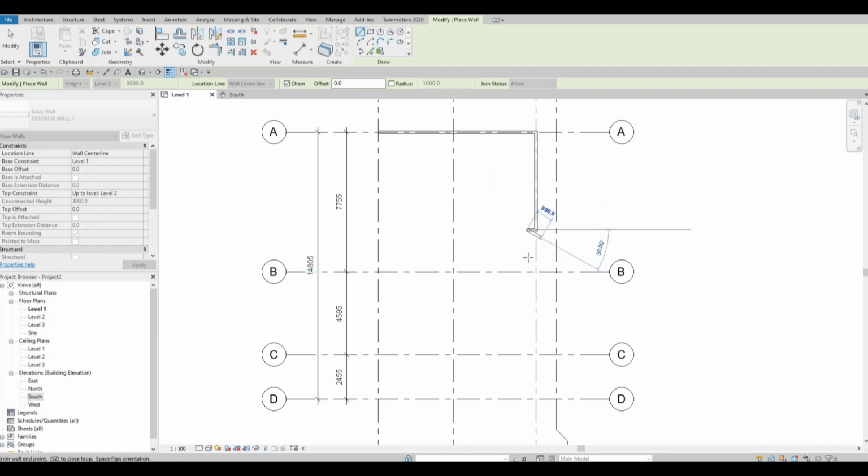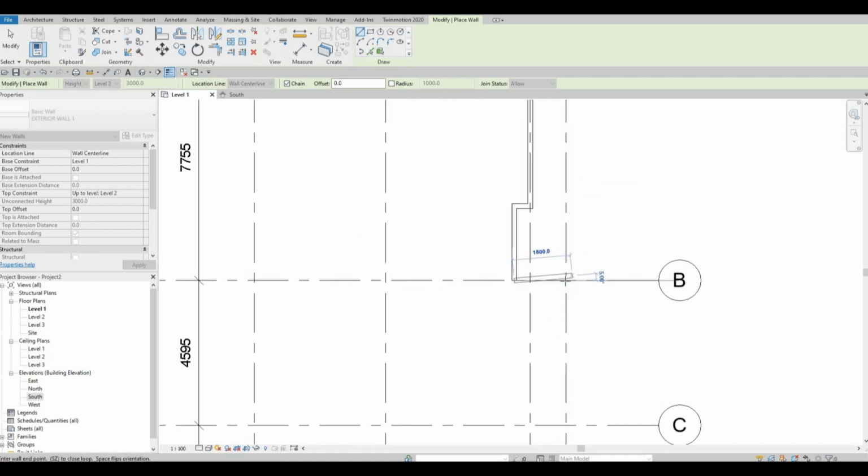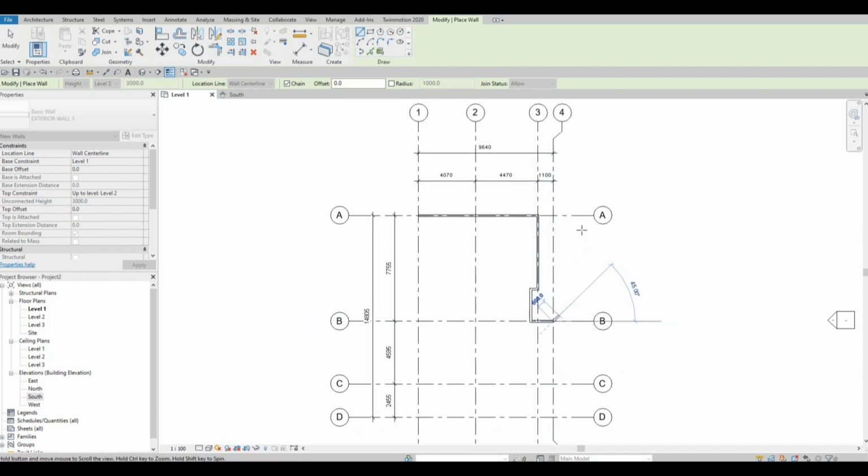So you can type in 500 from there and then go down to this spot, the B grid line. Just to repeat: 5,400, 500, and then pull it all the way down to grid line B, and from here turn right to B4, which is right here.